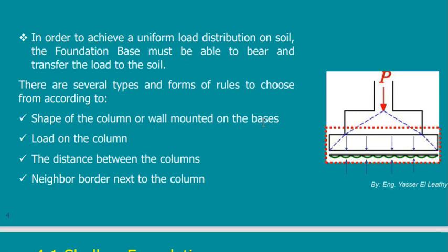The longer the cantilever, the more the moment. So the depth will be increased and the amount of concrete will be increased. So I need to have the foundation with the minimum cantilever outside of the column.